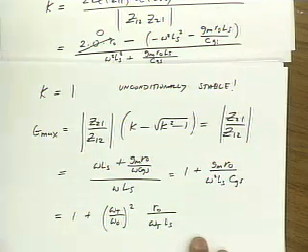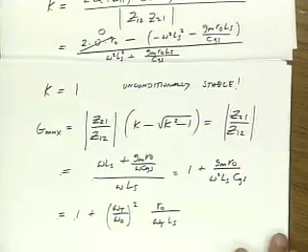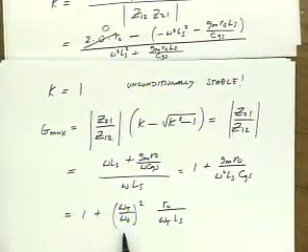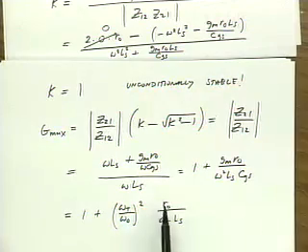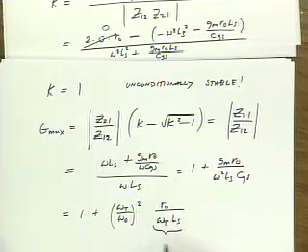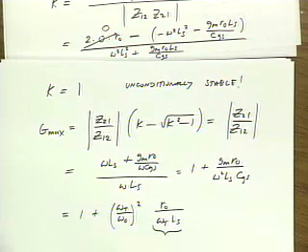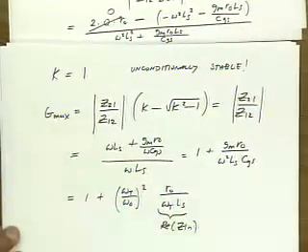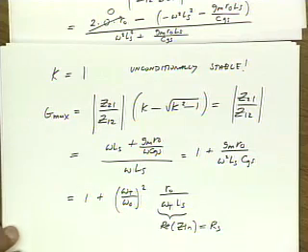It's basically a ratio of the omega T of the device and the operating frequency, and a ratio between Ro and a resistance equal to omega T Ls. Now remember omega T Ls, because it's going to be important. What we're going to show is this is actually equal to the real part of Z in. And we know that we get maximum gain when we impedance match, and so this is actually going to equal Rs, the source resistance. Okay? Any questions about this calculation?